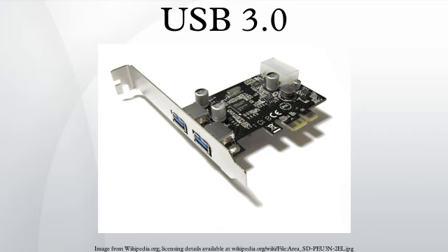The USB 3.0 specification is similar to USB 2.0 but with many improvements and an alternative implementation. Earlier USB concepts like endpoints and 4 transfer types are preserved, but the protocol and electrical interface are different. The specification defines a physically separate channel to carry USB 3.0 traffic. The changes in this specification make improvements in the following areas.